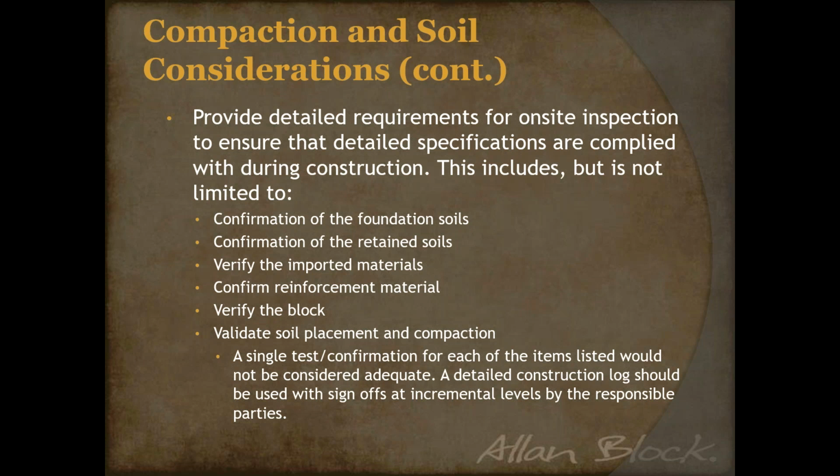So imported materials might only refer to the wall rock that we were talking about in that wall rock column, but it could also refer to the entire infill zone. If you were replacing that entire infill zone with a select fill, this is more common in fill applications because otherwise you do have to excavate quite a bit. But you have to put that dirt somewhere else if you're going to get rid of what soil is already on site.